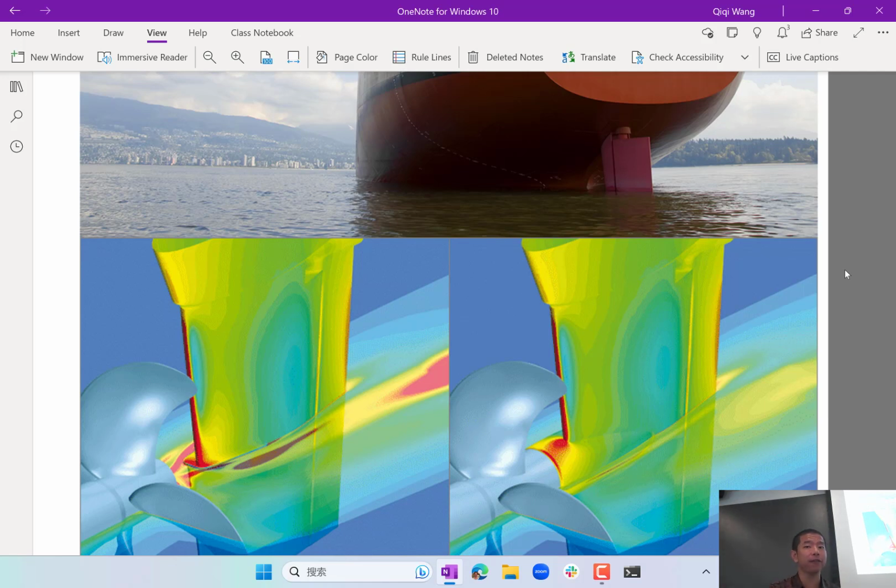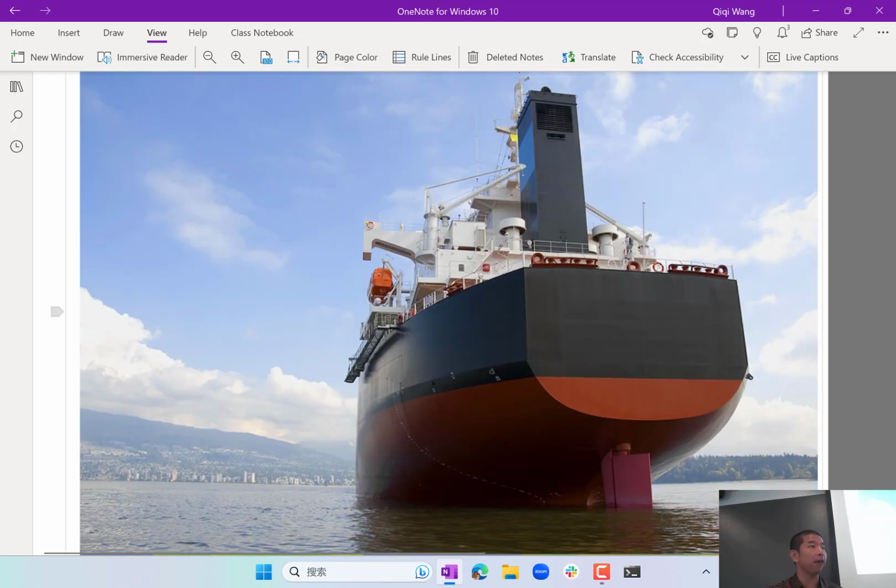There is another lift force on the ship itself, right? After the ship has changed orientation, it basically has an angle of attack relative to the water. And if it wants to turn left, then the angle of attack is going to induce a leftward lift force on the majority of the ship that actually changes its direction, that provides the centripetal force for the ship to actually turn. Okay, so next time if you want to explain why the Titanic sank, it did not have enough lift forces.